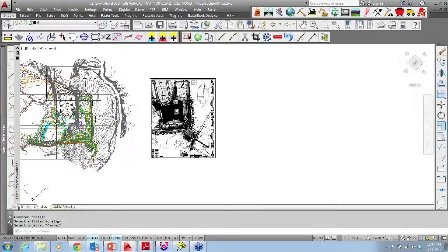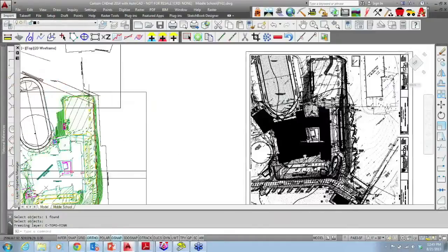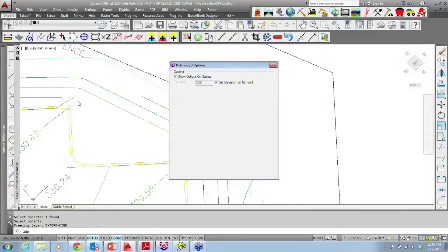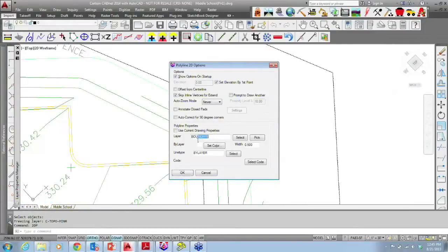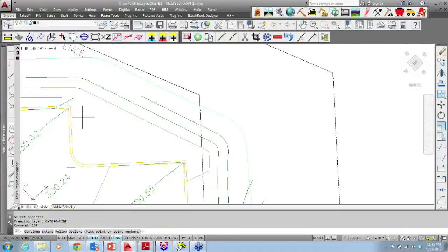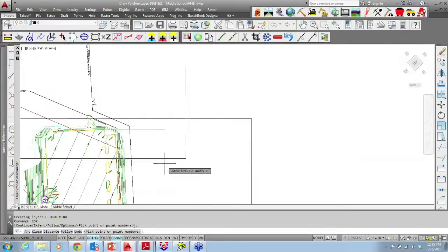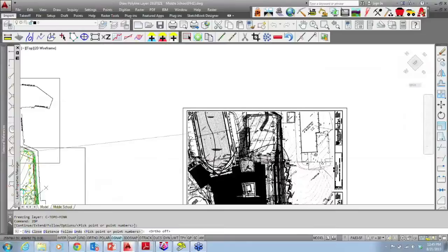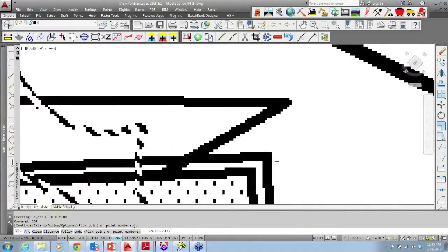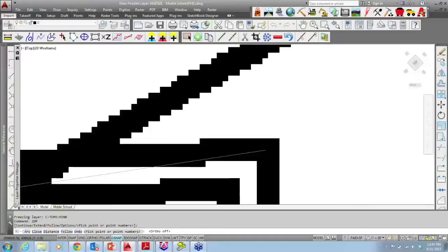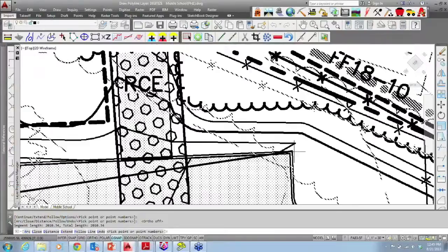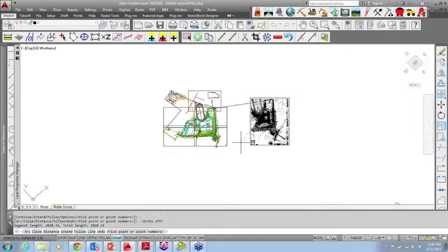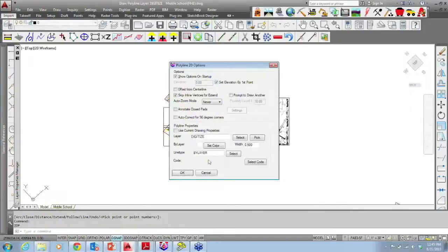Oh, well, I have to do this. I'm going to window up. Here I'm going to do layer off and just freeze my existing. And I'm going to draw a polyline. I'm going to do 2DP. And let's just call this digitize right there. And let's grab this one right there, turn the ortho off. Let's go look for that in this drawing right here. And I have to digitize 2 node points that are in my CAD drawing that also exist in my raster image. So I hit that one, hit return, and we'll do another one.